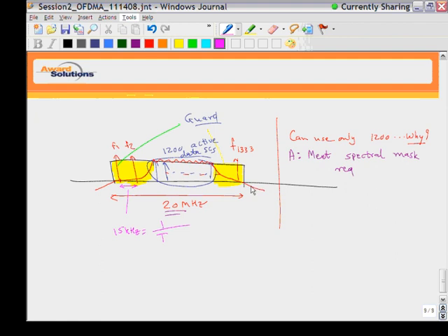By the time we reach the edge of our spectrum, the signal is very, very weak, and we are able to meet the FCC spectrum mask requirements. No interference to adjacent spectrum, because we are given only 20 megahertz of spectrum. We cannot start causing interference to the folks who are using this part of the spectrum, or who may be using the left edge of the spectrum, because this may be another operator. We do not own that spectrum.